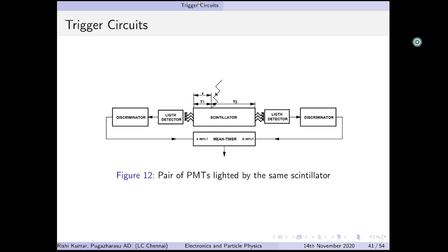So you have two different input pulses, and it arrives at this point. You can measure the time it takes from here to here and here to here. You subtract the time, you actually would measure the ratio between T1 and T2. So that's the idea that's going on here. We essentially want, in this case I'll say tau, which is t2 minus t1. This is what we're looking for.